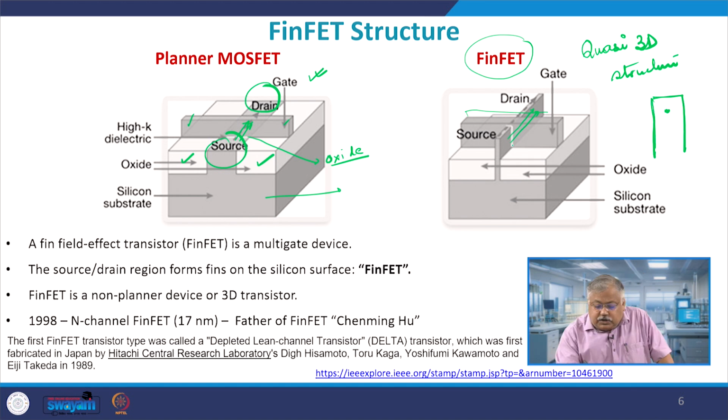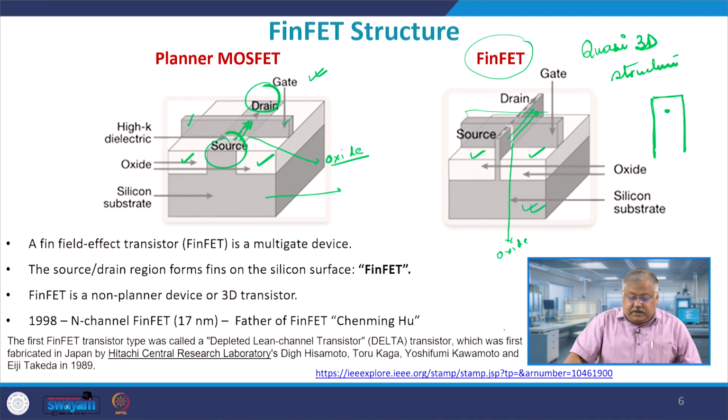And therefore, the thin white layer which you see here is the MOS oxide layer, and this is the STI, and then you have a silicon substrate here. So, this is basically a multi-gate device. Why multi-gate? Because now the gate, which is a metal gate, will have the source contact here and drain contact here, or you can have an elongated contact in this direction.